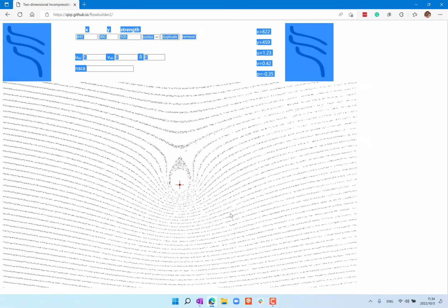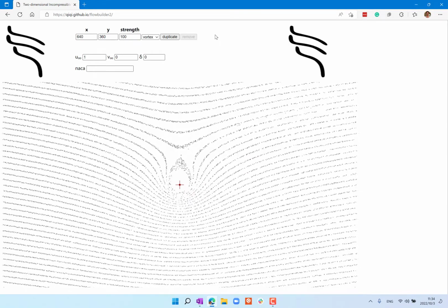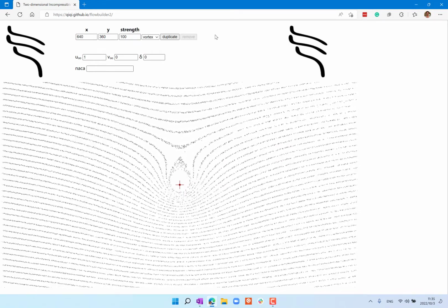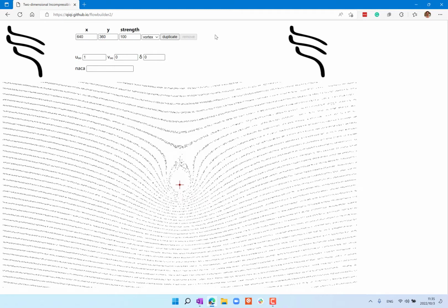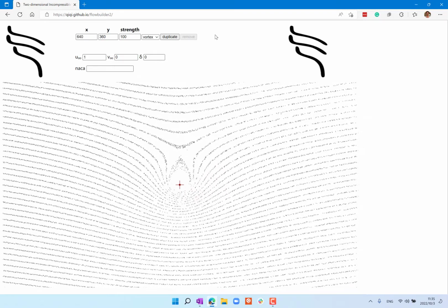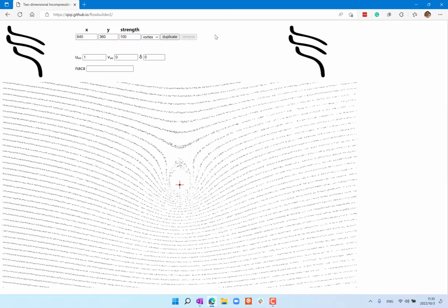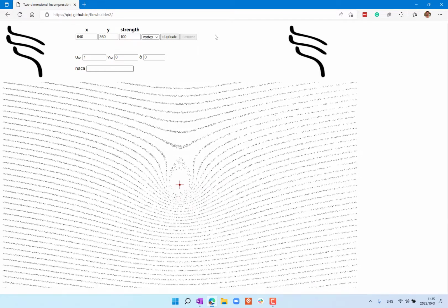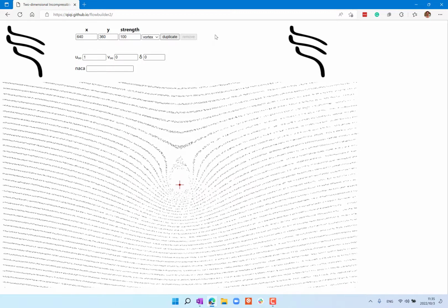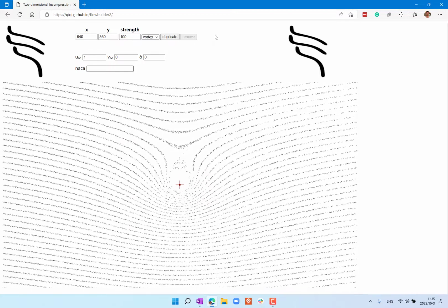That's actually the basic strategy we are going to be taking to study what the flow field is like around solid objects. That is, we try to place vortices inside the solid body, not outside of it, right? Inside the solid body, so that we match the contour of the solid body with the tangential direction of the flow field. And that actually gives us what the flow field is like around the solid object. Okay, and using Bernoulli, we can also see what the pressure distribution is like.